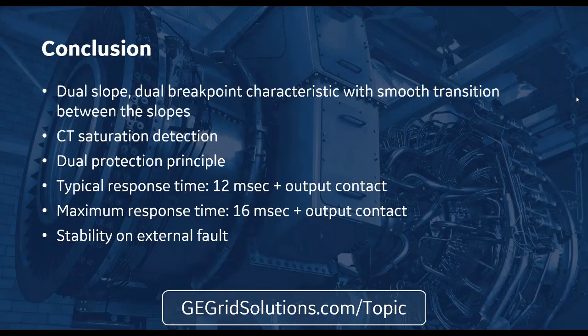Another question we had was high impedance protection. Where do I apply it? What voltage level does it matter? It really doesn't matter, right? Or any type of differential protection, right? It doesn't matter what voltage level. It's how important is that bus to your process, right? Do you really want that fault current to linger on for that coordination time delay if you don't have a bus protection on it? If you could deal with that, if a stability issue is okay to deal with, or if you're okay with tripping out your plant for a stability issue. Arc flash, if you're concerned about arc flash, and we should all be concerned about arc flash because it's a safety issue.